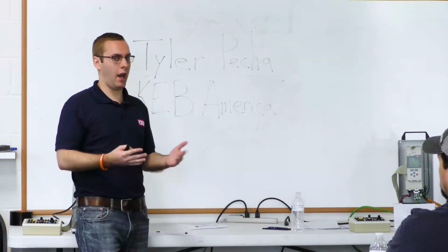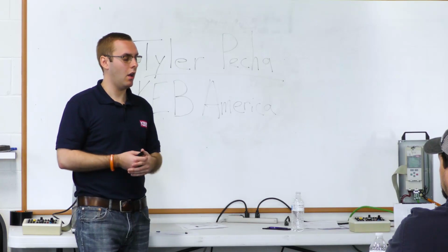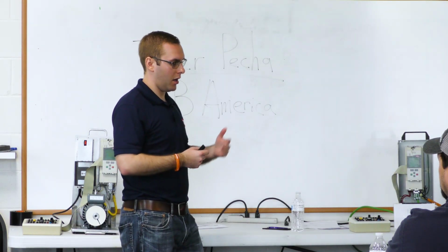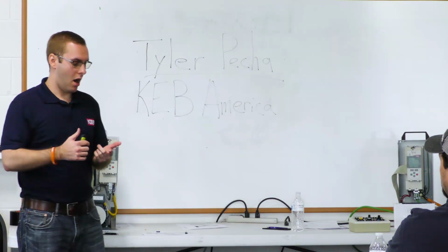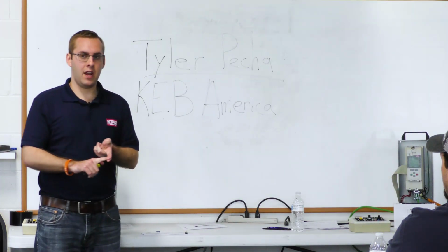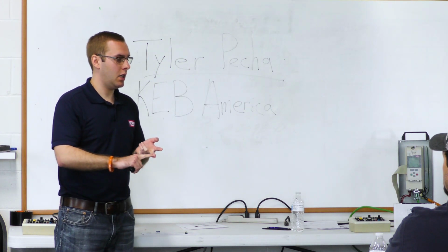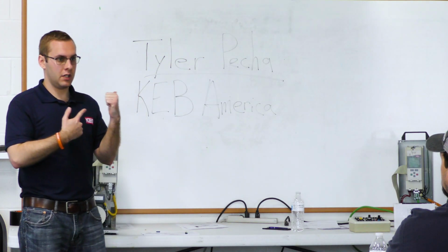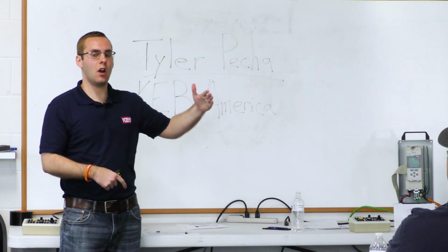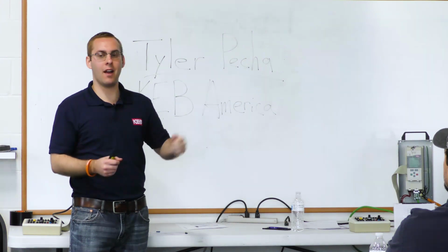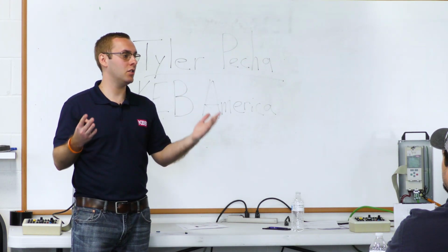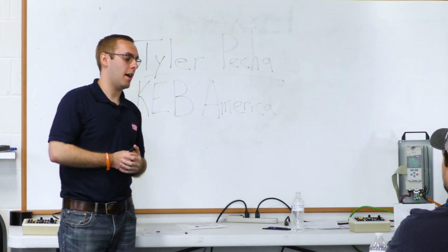Does everything power up okay? You didn't blow anything? Okay. So if all that looks good, then you can do your final connection, connect your motor, and power up everything there. The reason we have you power up independently is because a shorted phase on the motor, a shorted IGBT, will actually cause these fuses to blow. They'll travel through the drive, through the motor, back to the regens. So you'll get the new fuses, you'll put them in, you'll power back up, you'll blow the new fuses again. And you still don't know what the issue is.